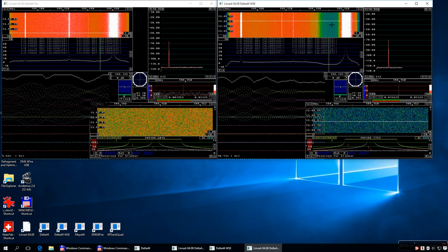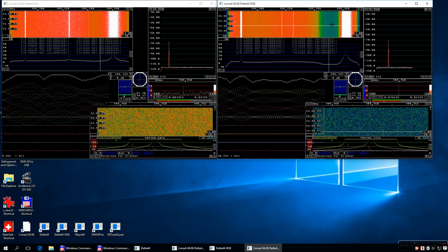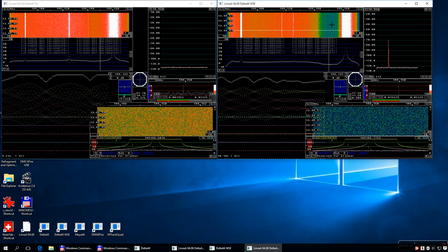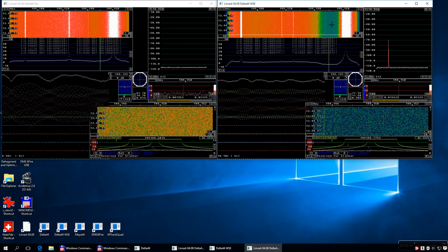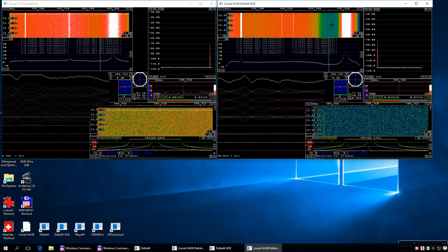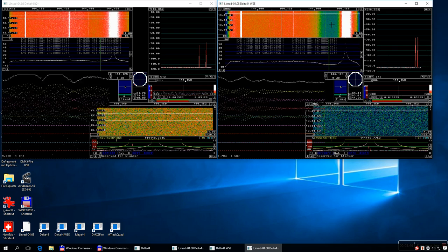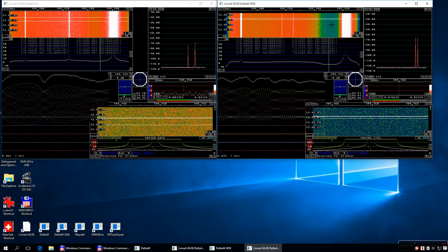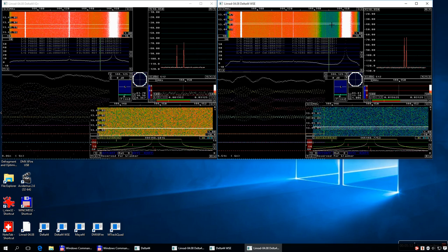That's the reciprocal mixing from the IQ Plus. That is the limiting factor in the IQ Plus, and it comes about 7 dB earlier than the limitation by saturation. And since there should be a low noise amplifier in front of the unit, it means that the reciprocal mixing isn't really a problem.